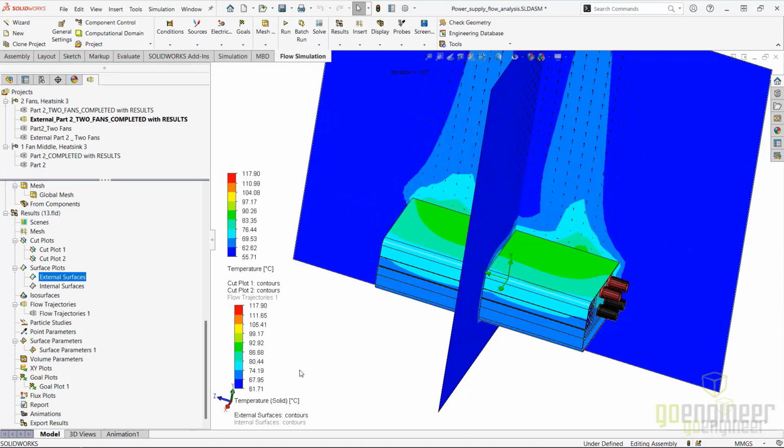All right, so we can see here that we have some heat transfer due to natural convection, and we can see that the direction vectors of the fluid medium here are pointing upward. So we're showing the direction of the air fields here. But we can probably conclude based off of the temperature differential that the majority of the heat transfer is being driven via the fans due to only a slight temperature difference, at least in the ICs, right?